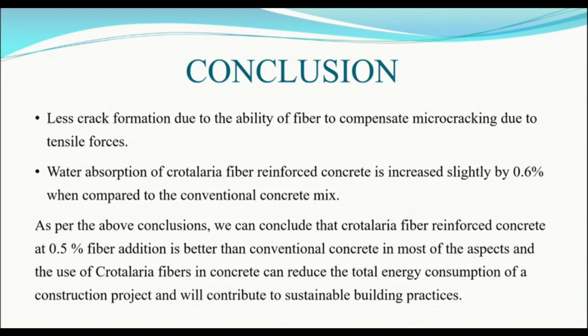However, for a particular mix, there is an optimal volume fraction of fibers that will give the maximum strength. In the case of mixes tested in this investigation, the optimum percentage of fiber was 0.5%. In general, it may be concluded that on increasing the percentage of fibers in the mix, the strength increases much better than conventional concrete in most aspects, which can be due to a variety of factors like characteristics of the fiber, nature of the cement-based matrix, the way of mixing, casting and curing of the composites, etc.